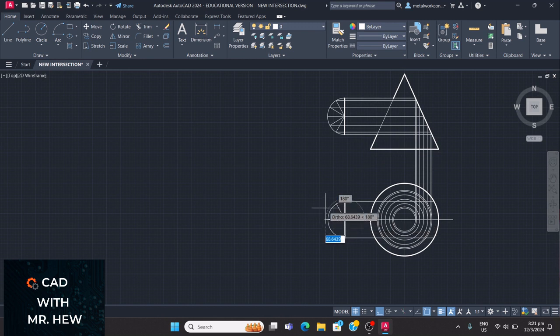I'm gonna go again. Line, 62 is the length that we're using, and the angle is 150. Good. Right. So we're gonna do the same thing below now. So we're gonna go line. So it's 62. 210. Right. Enter. Right. Wanna go again. Line, 62 as a length. 240 will be the angle.